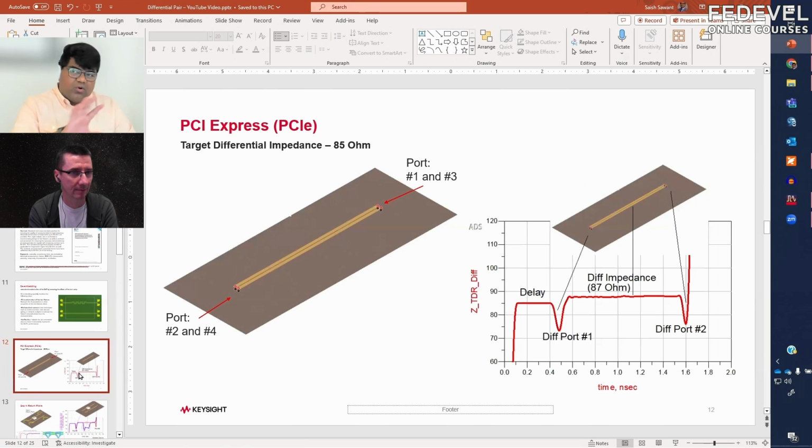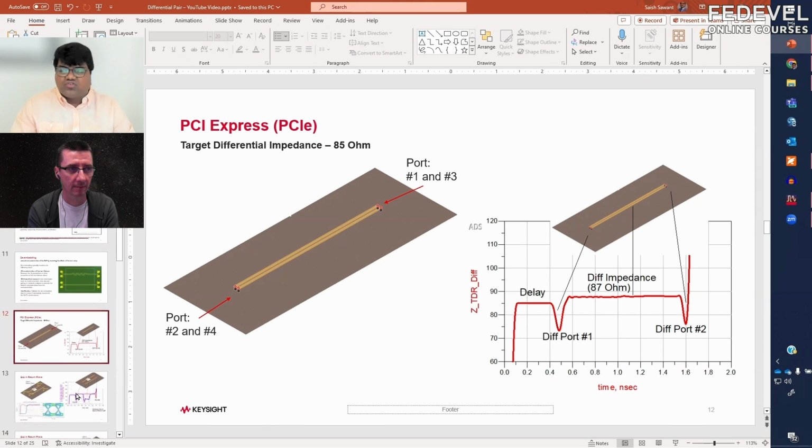So what I had here was, I don't have connectors in the example that I showed you. I was first going to make it very explicit that I don't have these test fixtures. I have not done de-embedding and all of that. So in all the results that you will see, you'll see the profile of the ports' effect. You'll also see the impedance, whatever we are going to discuss. I had this as an initial slide basically, but this is important yet boring stuff, or unknown stuff. I understand.